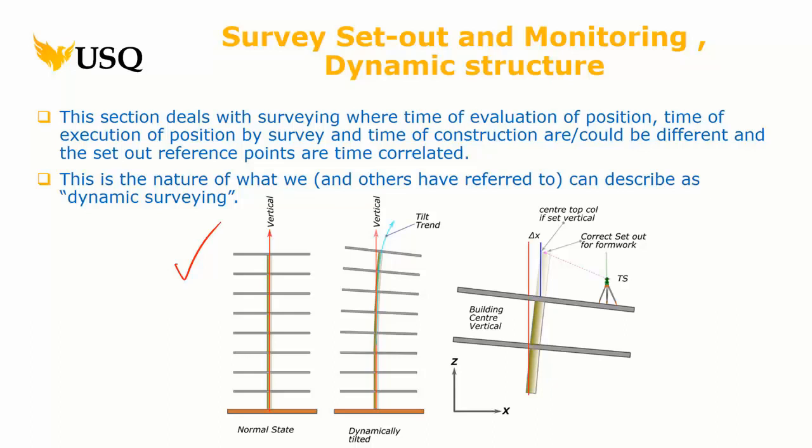So your trick is, how do you get the formwork, and this is formwork at this moment, just imagine circular column formwork, right, for simplicity. How do you actually get this formwork up here so that when the building straightens up, it actually is truly vertical? You see the total station, it looks a bit skew, right? So it's not horizontal for a start, right? But its vertical plane is vertical. If you sort of keep this in your head a little bit.